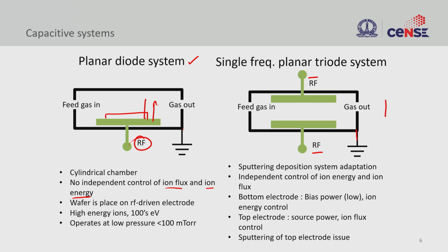So if you remember, when you energize the electrode, you will have electrons getting accelerated out, but you will have ions that are coming in. The high energy ions are going to hit this plate. When they hit the plate with very large energy, you will have sputtering. You actually want only etching, chemical etching, let's say, but in this case you are going to have physical etching, and physical etching means there is no selectivity. So this is going to actually remove all the material from this.